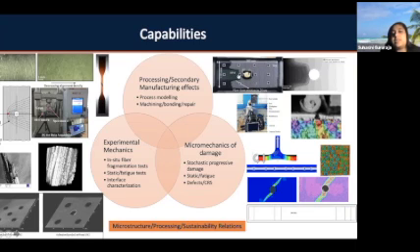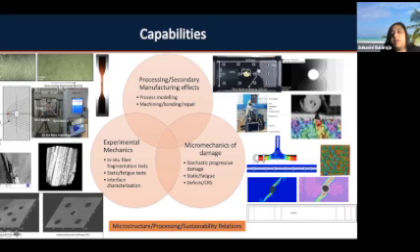And what we were interested in was looking at something like this. So if you have a geometry like a plate with a hole, what would typically happen, if you do not have a good process modeling setup, is you would end up having a region of a dry patch, for example, right after the hole. So typically what would be required is another inlet over here that opens up the moment the resin comes to this region, and then you would be able to optimize the flow process in a more efficient way.